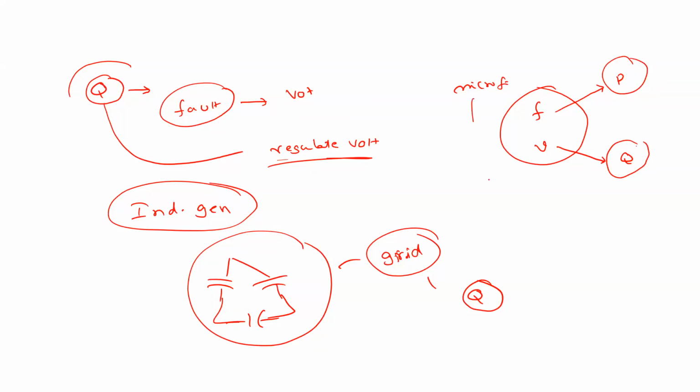So that's why in most microgrid applications we have battery energy storage systems present. What is the objective of these? Whenever there are fluctuations in the grid, the energy stored in the battery is given to the grid. If frequency fluctuations are there, some active power is injected into the grid, or excess active power generated in the grid is injected into the battery energy storage system, so that the frequency fluctuations can be minimized.